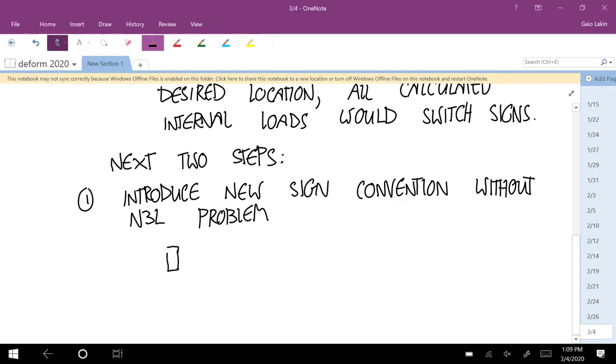So when you think about isolating a point on the beam, you can think about it as being an infinitesimal sliver. Okay, that is a finite sliver, but imagine it being infinitesimally thin. Then a positive value of what we were just calling the x component of the force before, on this side would be this way, and this side would be this way, and we'll just call that capital T for tension.